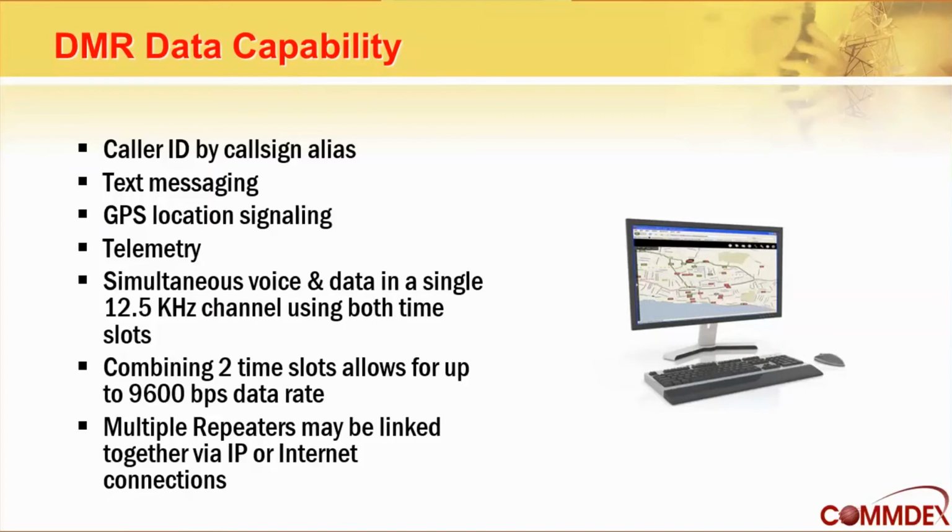And one thing that's unique about DMR is you can either put voice and data on separate time slots, or you can combine 2 time slots together to get an improved data rate for data. Also, a lot of people don't realize, but DMR can also support wide area systems and do trunking.